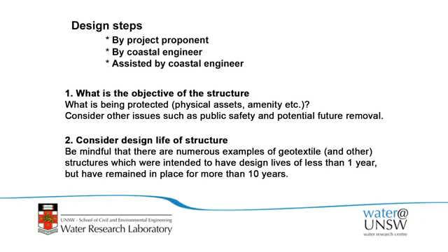So the first step I'd say is, what is the objective of the structure? It sounds pretty obvious, but at least write down or document why you want to build it, other than just some residents screaming that they want coastal protection. It needs to be at least a bit of a justification. So what is it that's being protected? So assets or beach amenity, and consider other issues such as public safety and how you might remove the works